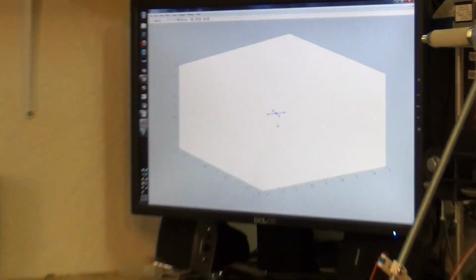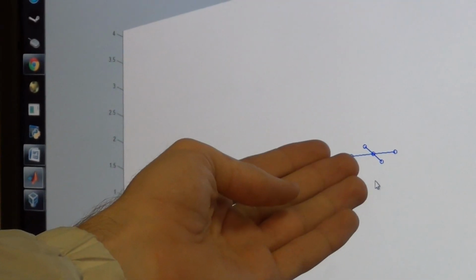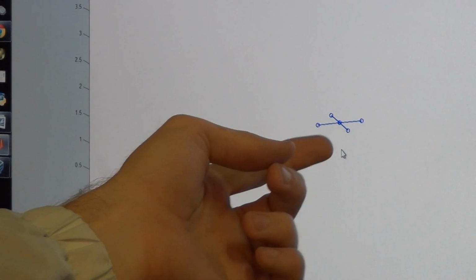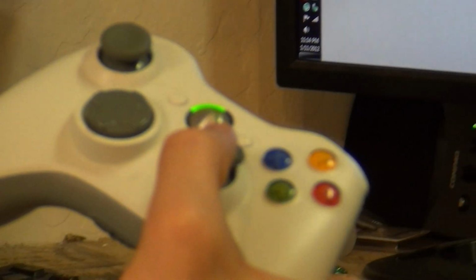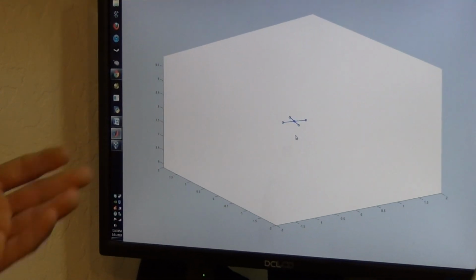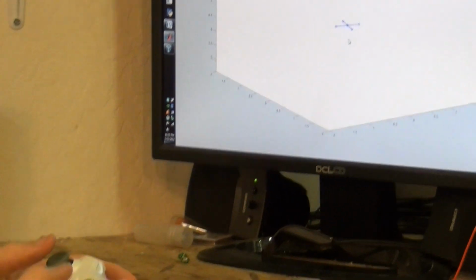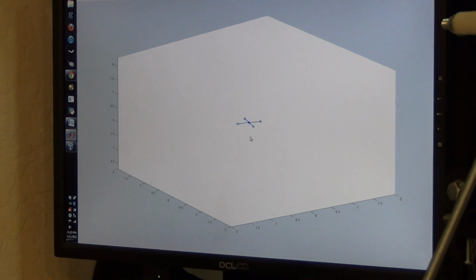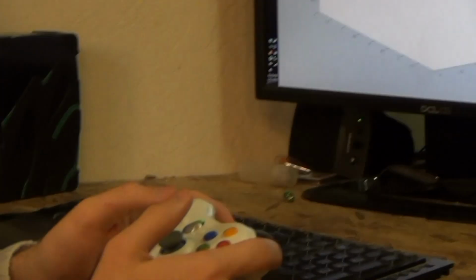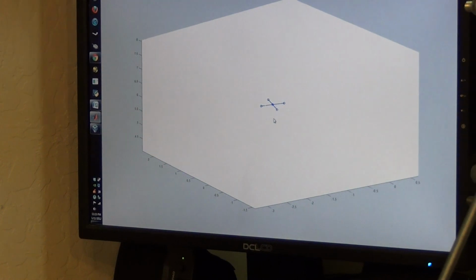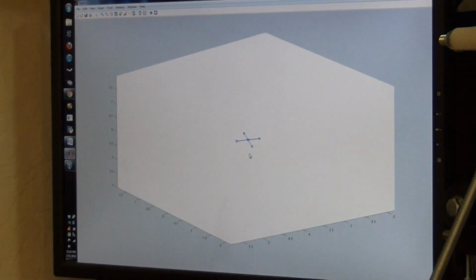And then there's the height command if I make it go up. The way I have it is as a fixed axis to the center point of the quadcopter, so you can see it going up the z-axis as I command an up position. And of course, there's a PID controller for the z, and it'll have a little bit of overshoot and then resettle. Then the one which is a little bit more complicated, which we played around with, is the roll and then the pitch. And as you can tell, it works.